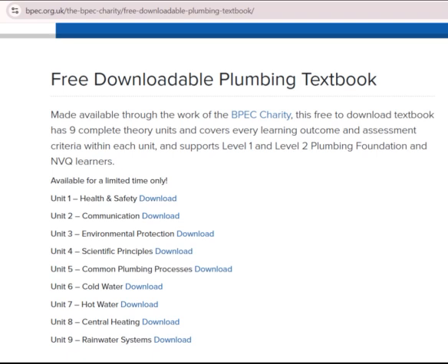Modern fully pumped systems would not work properly if the pump was positioned on the return, and the vent-cold feed arrangement on open-vented systems dictates the position on the flow pipe. Please see diagram on page 566. AC 2.3, State the system layout features for filling and venting systems.